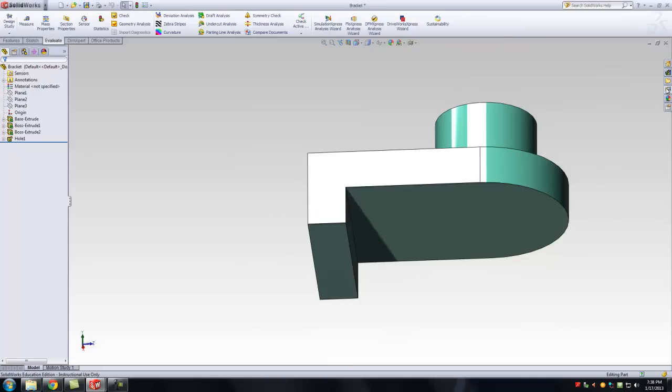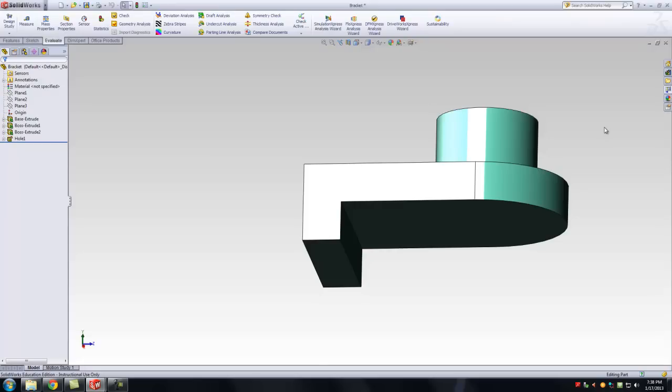The cool piece about that is sometimes if we have slanted surfaces, right, that if I'm looking at them from the top, they're not really normal to that plane, right? From the top, they're probably slanted. I can actually add a view normal to that slant, so I can dimension it nicely.